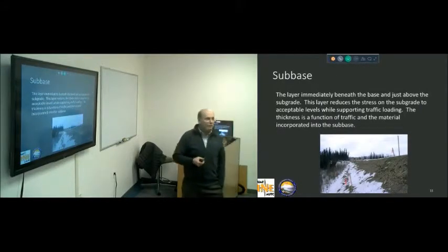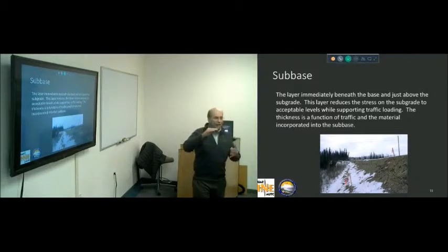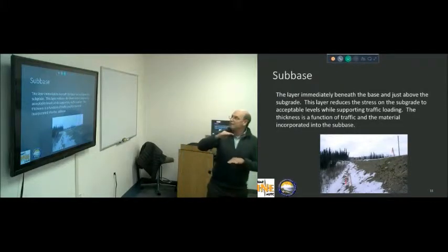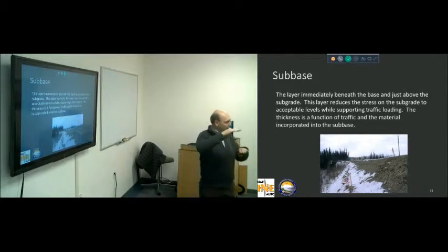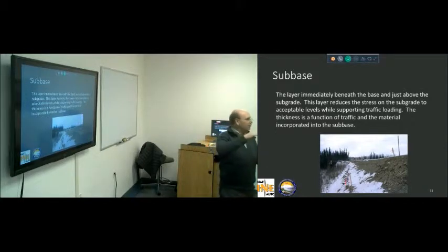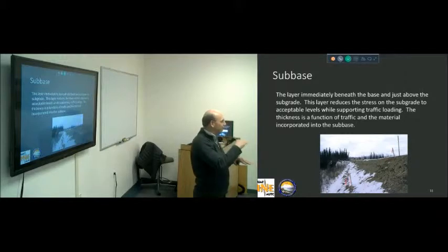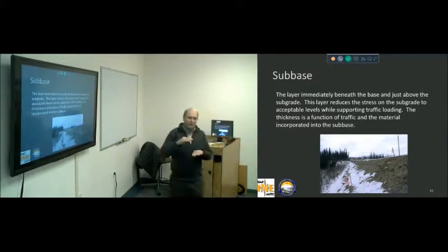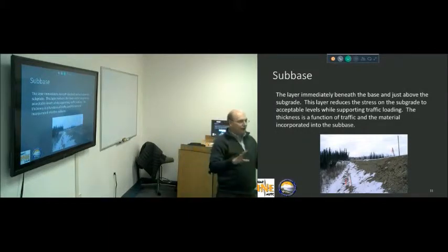The subbase is that layer between the bottom of the base course and the top of the subgrade. Okay? Its primary function is, again, to reduce the load on the subgrade such that it can withstand that, based on the material it is. Now, this is where a pavement engineer and the Blue Book, our specifications, part ways a little bit. In the Blue Book, subgrade is considered the natural ground. Okay? It's not the embankment.